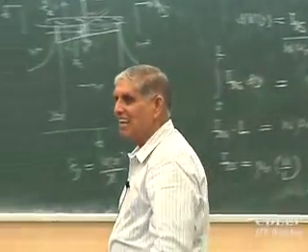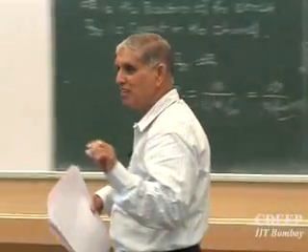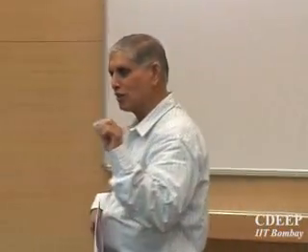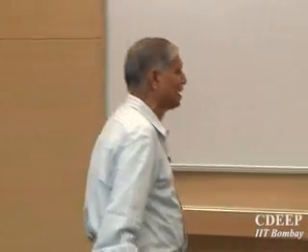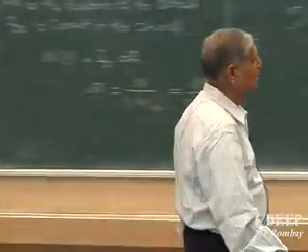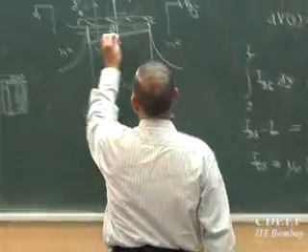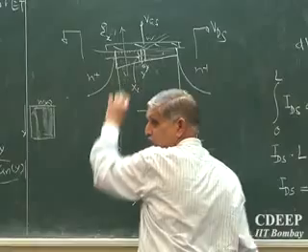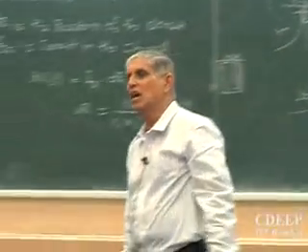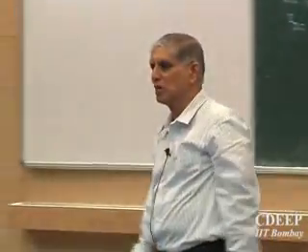But in reality I said mu n is also a function of electric field, carriers, all that, but that's not the worry I am really having. I have more worries in mu n than what I said earlier. This inversion layer I have shown you very thick, but typically it will be 1000 angstroms, 0.1 micron or so.